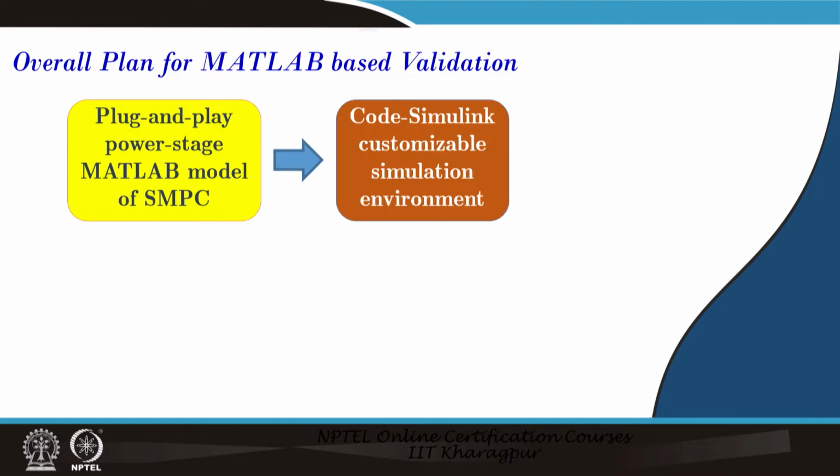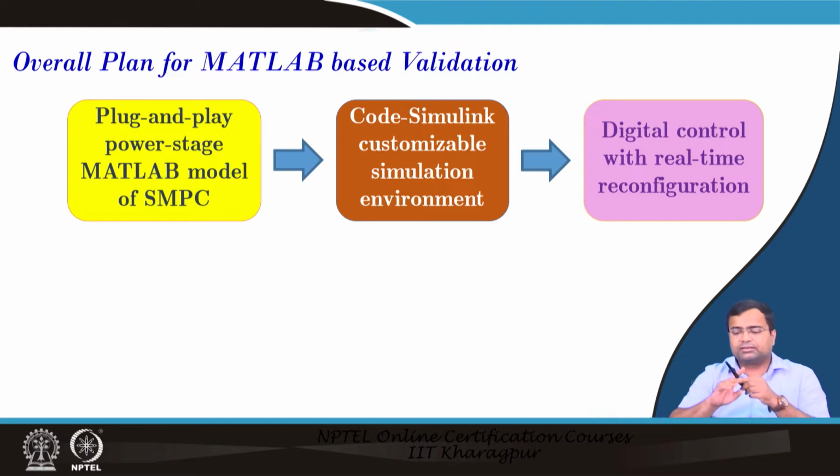Next we also have code and Simulink customizable simulation environment, where we want to run the Simulink model from the .m file itself, and there we want to plug in all the parameters of the buck DC-DC converter. All these steps will be discussed in detail. The third one, we also want to implement digital control, where we can also keep some real time reconfiguration possibility, but we want to implement digital control in Simulink.